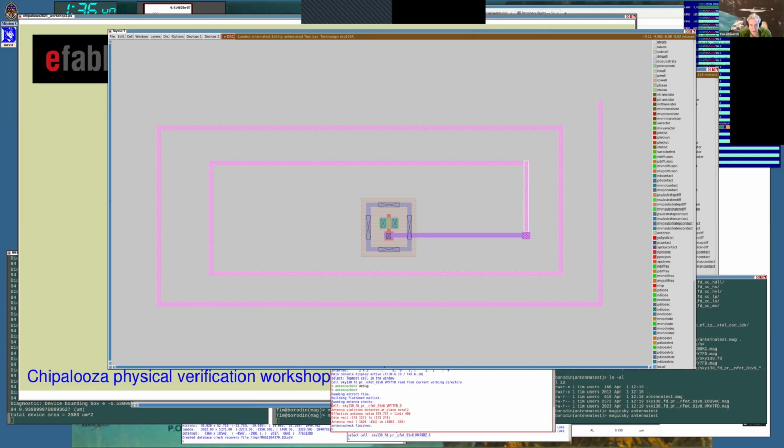And because I said debug, I get all the information I need about that antenna violation, which is, here's the cell whose gate is going to get blown by that antenna. The antenna violation is detected at plane metal 2, which means my problem exists here on metal 2. The effective antenna ratio is 970, where the limit is 400. So I've got a wire that's somewhat more than twice as long as would be needed to blow out that transistor. And then it tells me where is the gate and where is the antenna, so I can track down where those are and fix it. And that's how antenna violations are detected.